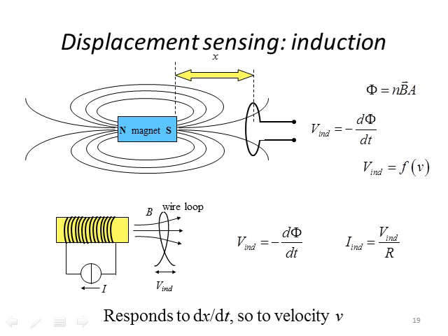Now the inductive sensors, you can have two types of sensors. I show two here. One is a magnet, one is an electromagnet. And in this case, as I said earlier, the voltage induced at the output of this coil is a time derivative of the flux, so this is really measuring velocity of the coil as it's moving. And the same general rules apply to also the electromagnet that's on the bottom. So the coil is moving and we can measure the velocity of that coil by the B field that's being modified.